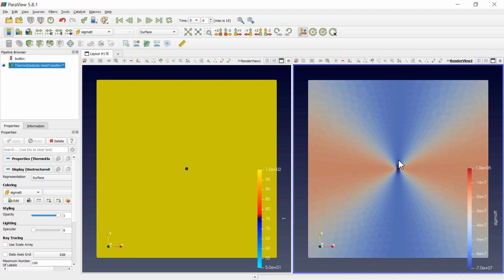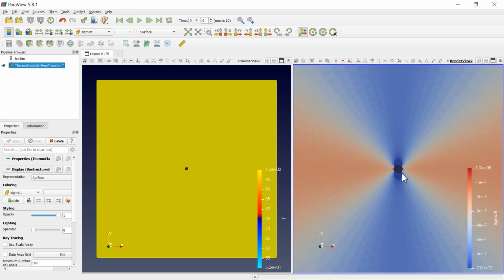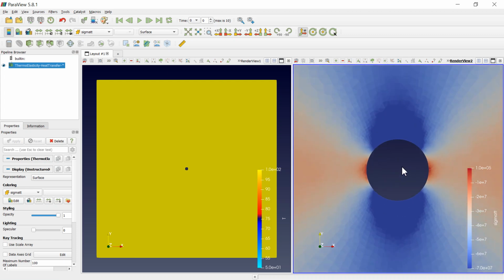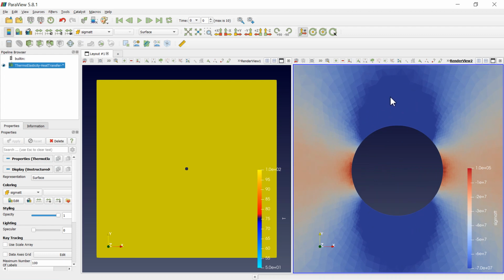Here at the right, we're looking at the tangential stress, sigma theta theta. This is what you see over here. And if I zoom in into the wellbore, we see that we have quite a bit of stress over here, the negative values, compression stress, and in this region we have lower stresses and even getting to the value of tension, something that we would expect from the Kirsch solution. This is the initial step.